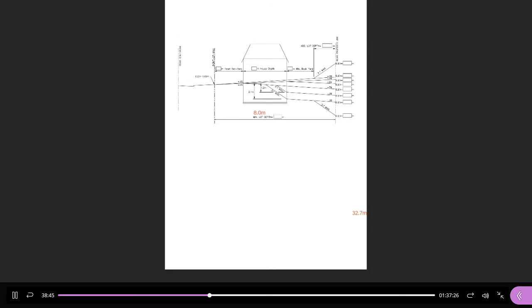Hang on a second. So let me draw that line, right? So from the front of the lot, you can't drain toward the house. Do you see that red line? That's not allowed. It has to drain away from the building. Your front lawn always falls toward the road. Okay, let me get rid of that.